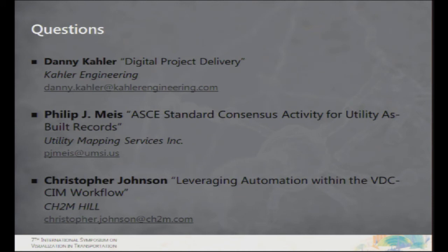Well, you have to demonstrate the value of going to 3D during project development. And there are tools that are evolving right now that let you collect existing utility information in 3D. We do what's called a subsurface utility engineering process, which involves going out and collecting the data. You start with the record data, then you do a surface reconnaissance of all the surface facilities and associate them with the records. Then you go out with geophysical equipment and map everything out in very good detail in 3D. So on a project-by-project basis, you can have very good data in 2D and in 3D for your project development.